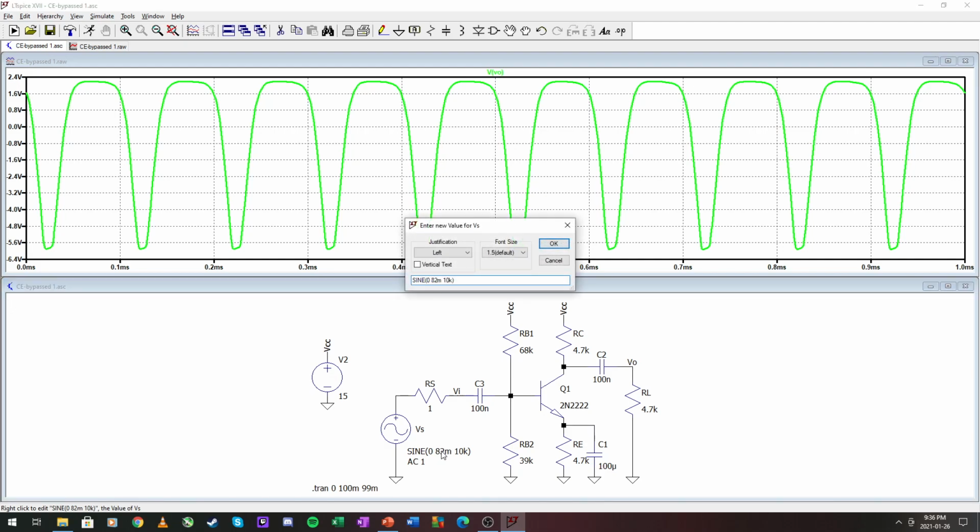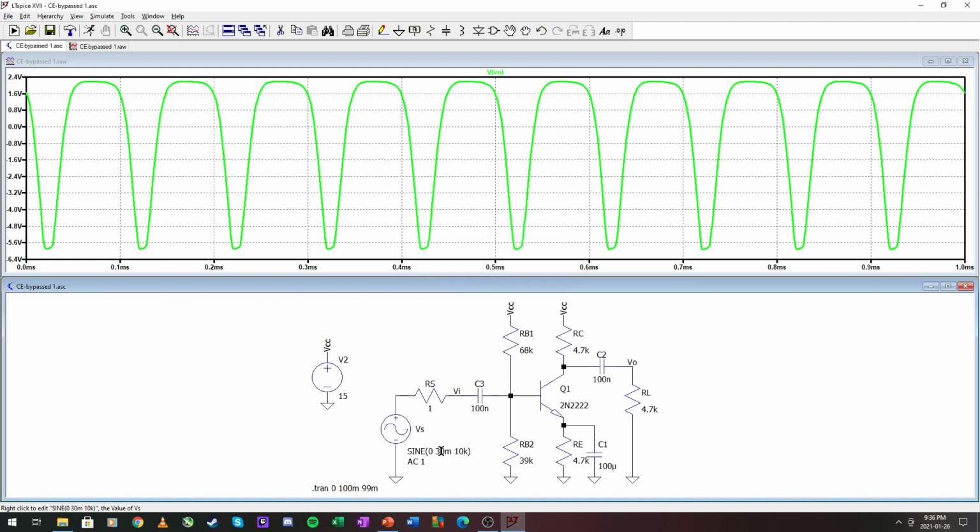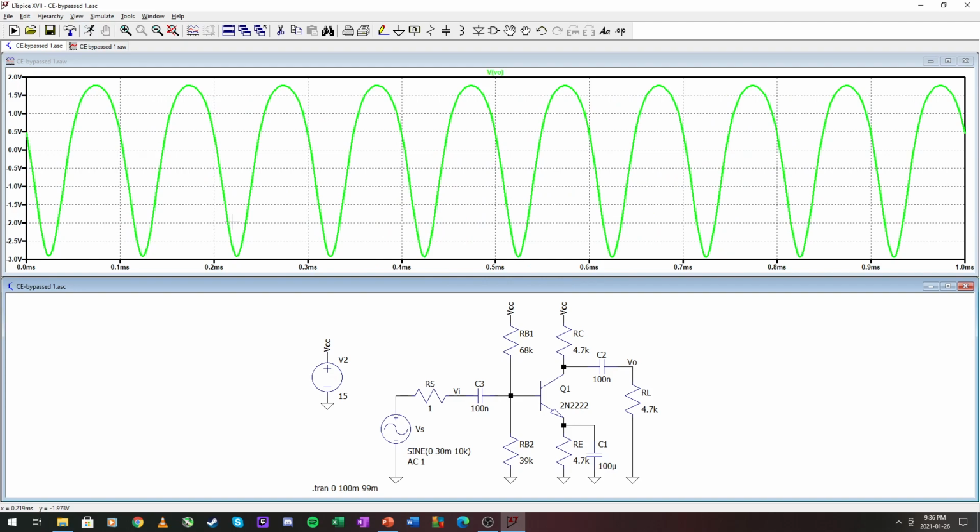Right, so the other one we had here was 50 millivolts. 50 millivolts, oh, there is our signal back like we had it. Here close to -3, up here moving towards 1. I'd call that 1.7-ish. And we have no clipping, but it's seriously non-linear.